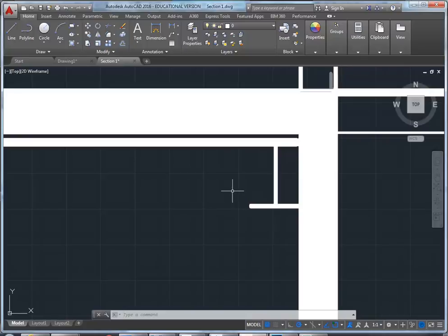Floor joists? So it's an option, but if you're going to do that, then the services, the lighting and the plumbing and everything else, it needs to be exposed. So you have to model that in and not have a ceiling, which is another way of doing it. So you can do that if you want to, and exposed floor structures can be really nice, but you need to make that decision fairly early, because you have to allow for the modelling. Otherwise, put a ceiling in and you don't need to worry about it.